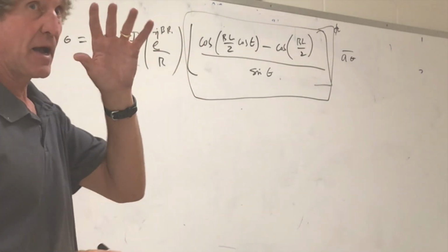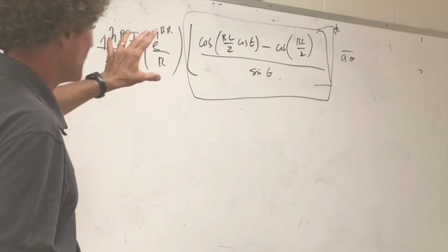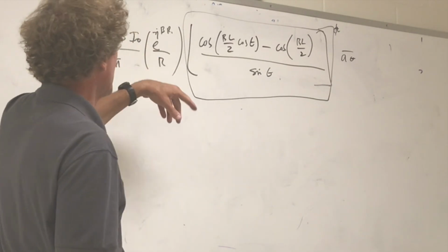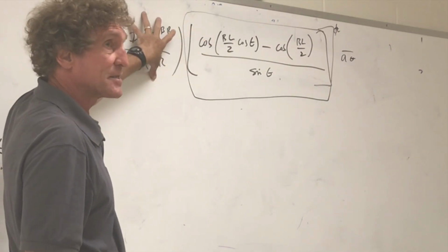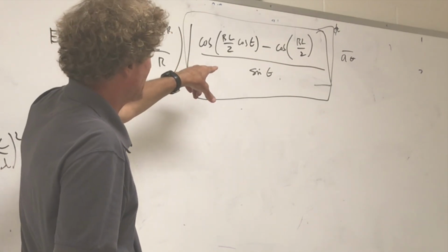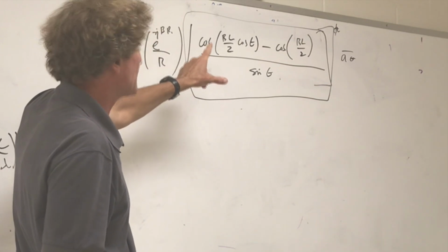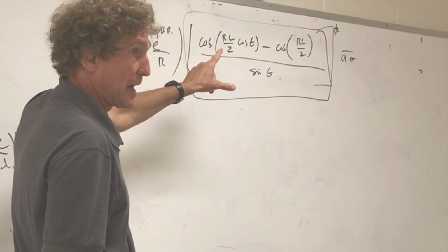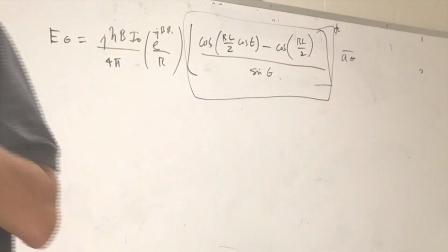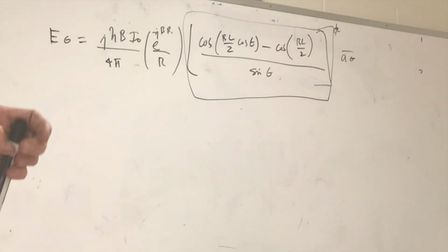So this is where it gets hairy. By the way, that right there, that's the electric field. The power pattern would square everything. All this stuff, when you square it, is just going to have an I squared function over r squared. This is not of importance to what we're about to do. When you square that, you get something that you don't know what it looks like. It depends on beta L. You with me, class? Depends on that tremendously. And that pattern is called the electric field or magnetic field pattern. The one in the book that Wentworth always goes for is the power pattern.